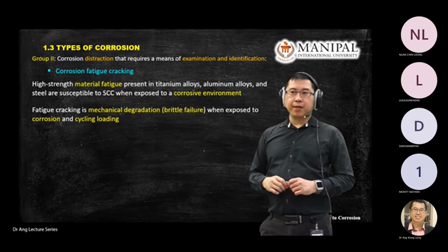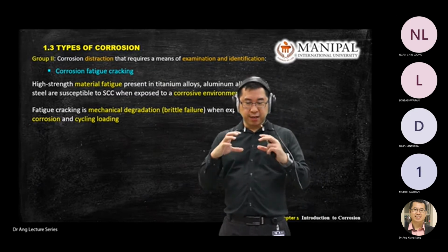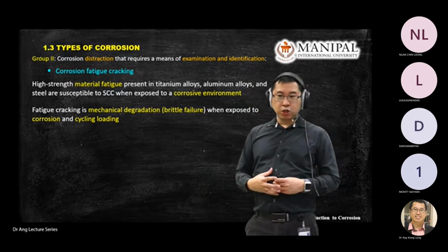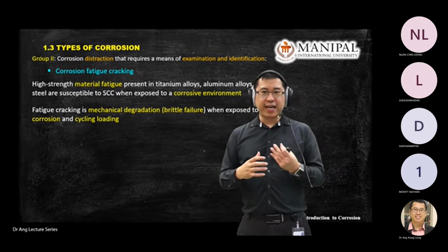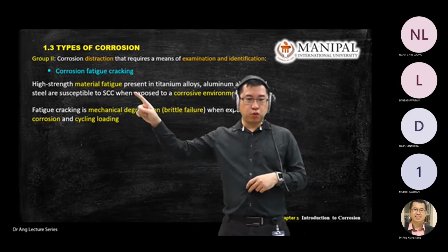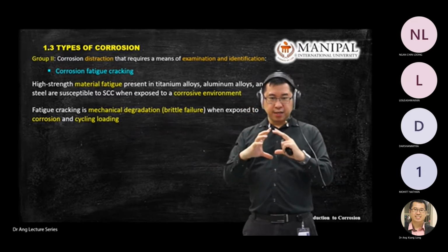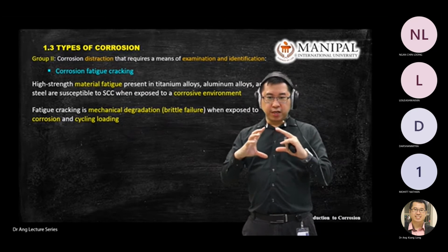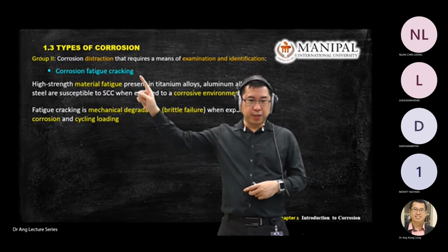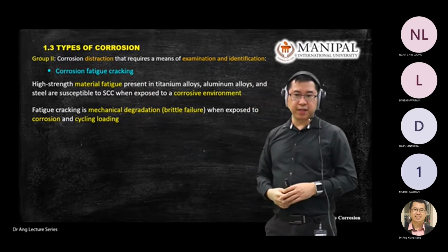Sometimes under temperature also, because you know metals expand under hot temperature and contract when we have a cold or lower temperature. So when you deliver a solution that can change the temperature of the material, it also will contribute to corrosion fatigue, but you need a corrosive environment. As long as there is continuous loading, or dynamic loading there, it can be categorized under corrosion fatigue cracking.